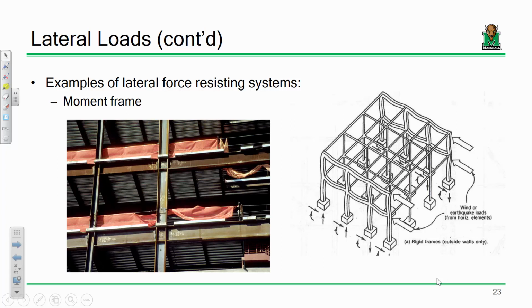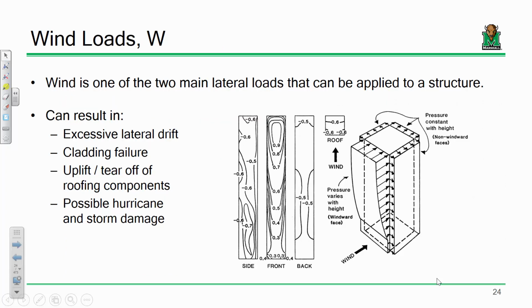but they are a little bit more expensive. I know that sometimes seems counterintuitive because there's not a big brace in the middle of the building, so shouldn't the brace be more expensive than this? And the answer is no, just because of all the complex welding and stuff that needs to be done over and over again. Brace frames are a lot easier from a fabrication perspective.